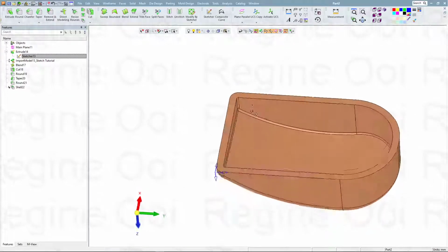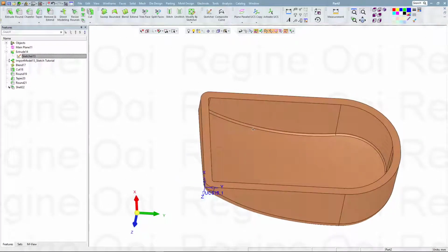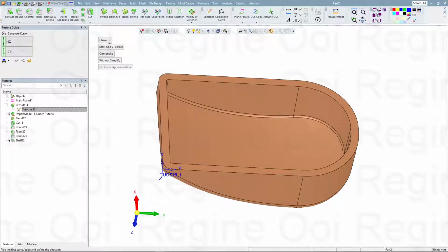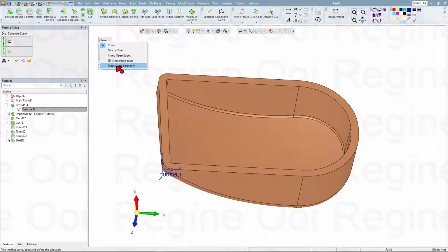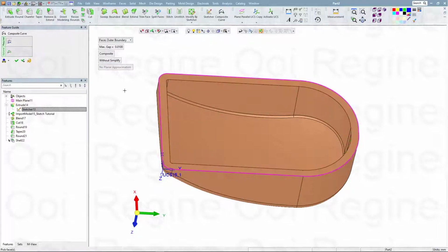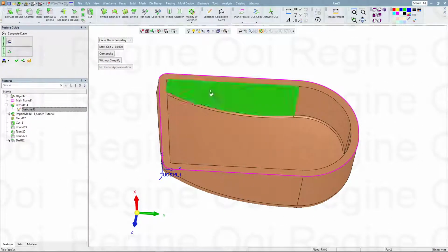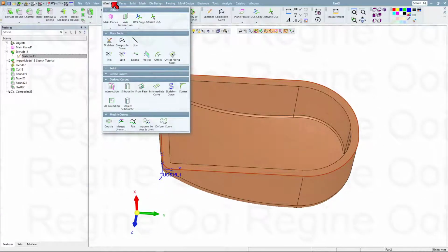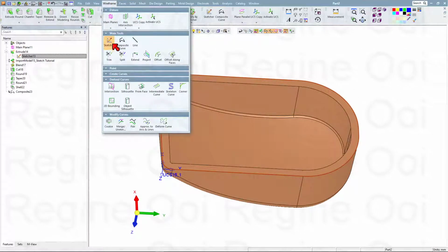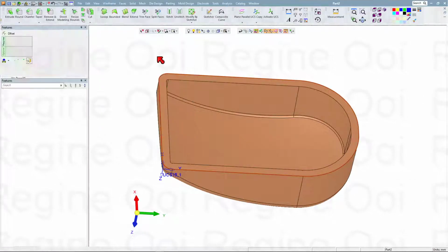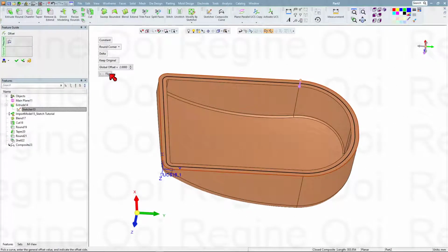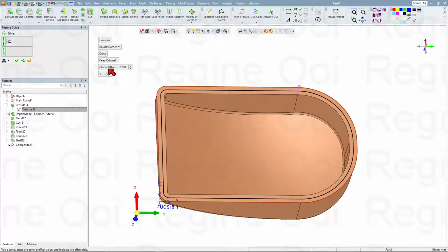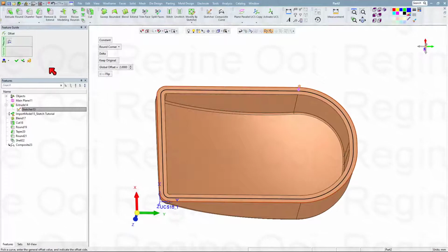And then I will turn to the back side. Wireframe, composite curve. Select faces outer boundary. Select this and automatically get the composite curve. Okay. After that, I will get the wireframe offset. So flip to the center here with the offset 2 mm.